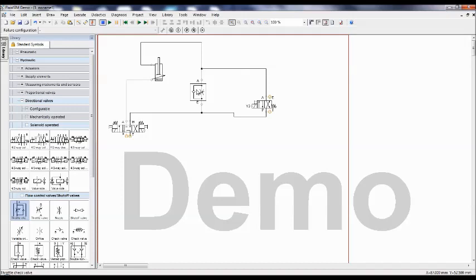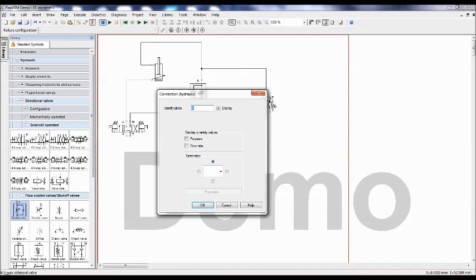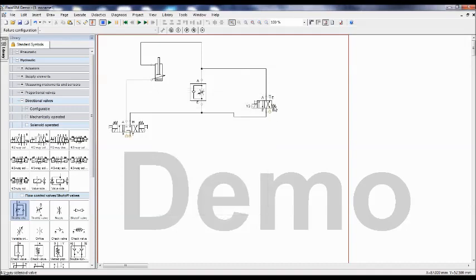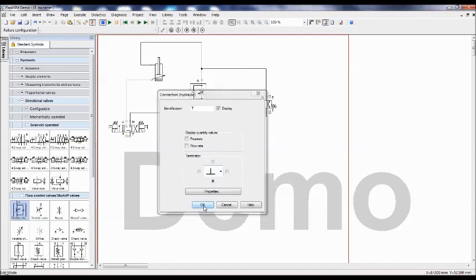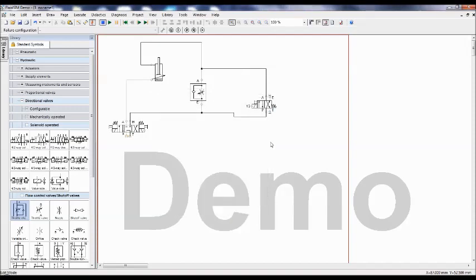So what you can write is, when Y3 is off, slow speed, when Y3 is on, high speed. That is the requirement. Other two ports we can block. So double click on it and then go to the terminator, take the terminator. A 2x2 valve is also enough, but it's not available in the lab, so we are using 4x2 as a 2x2 valve.